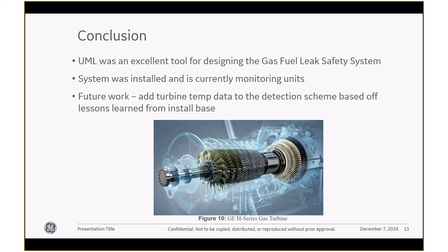One of the units that we're monitoring is located next to a solid waste treatment facility. Unfortunately, the solid waste treatment facility releases a lot of hydrocarbons into the air. Not only does the plant smell like sewage, but these unburned hydrocarbons were originally being picked up by our sensors. Because we didn't include environmental impacts in our UML fully dressed use case, this caused some issues. Luckily, we were able to identify the issues quickly and go back and fix it. But this was one bit of lessons learned from utilizing UML.